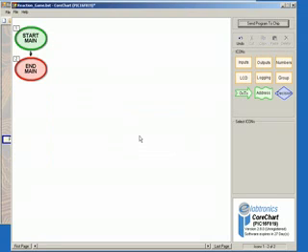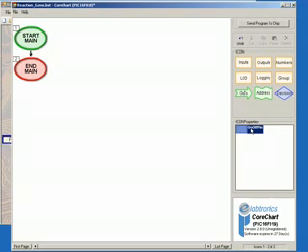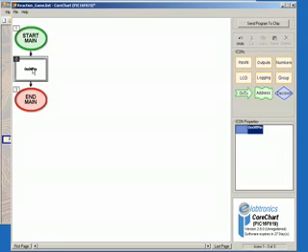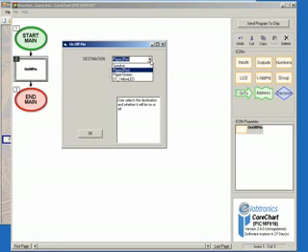We'll start off by clicking on the outputs icon in the icons menu, then clicking on on-off pin, and place this in our program by clicking on the black arrow below Start Main. We'll now double click on this icon to bring up its options, and select Speaker in the destination field and select On, and then click OK.